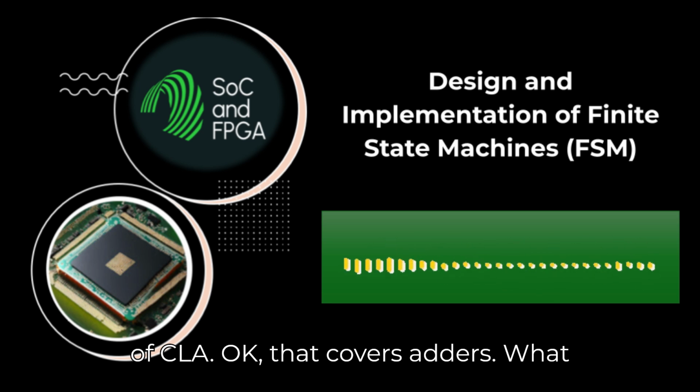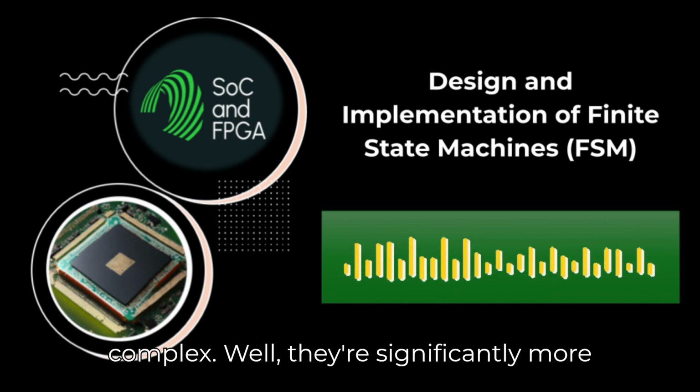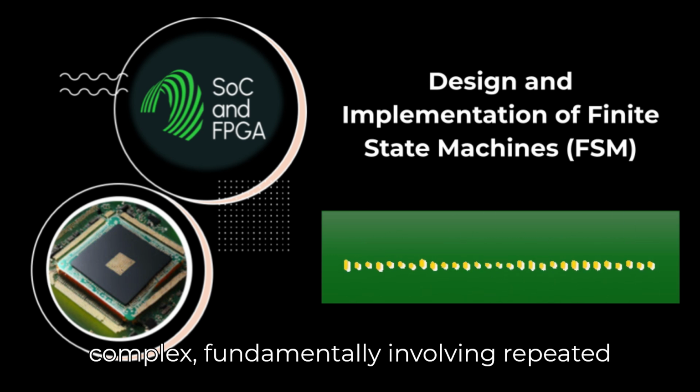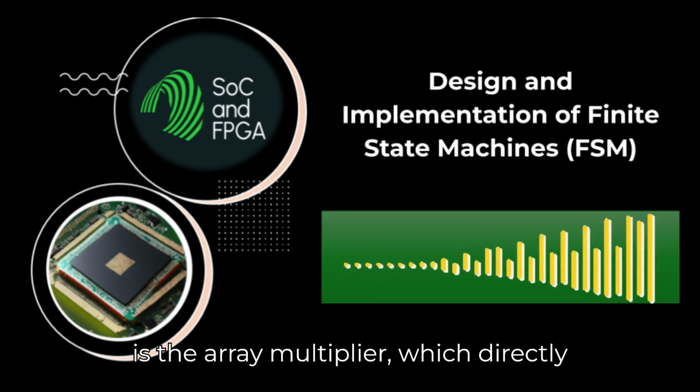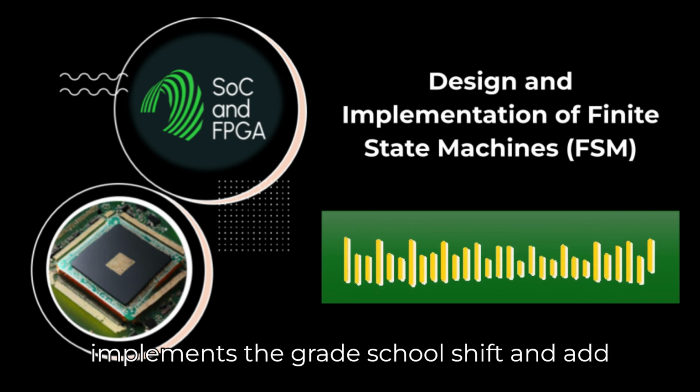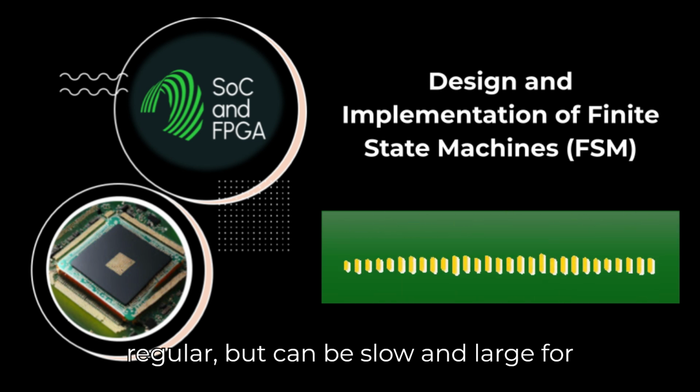Okay, that covers adders. What about multipliers? They seem much more complex. Well, they're significantly more complex, fundamentally involving repeated additions and shifting. A basic approach is the array multiplier, which directly implements the grade school shift and add algorithm using an array of adders. It's regular but can be slow and large for wide inputs.